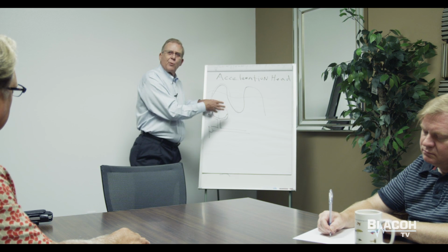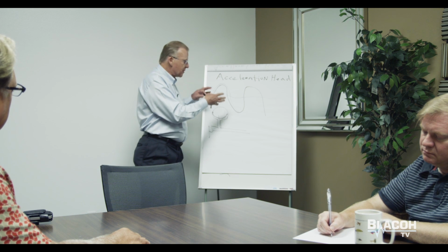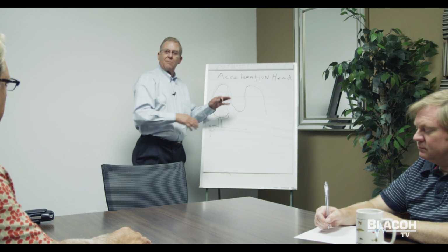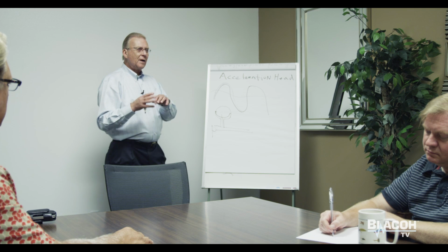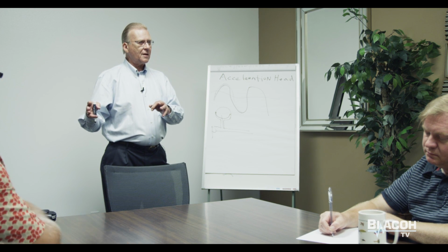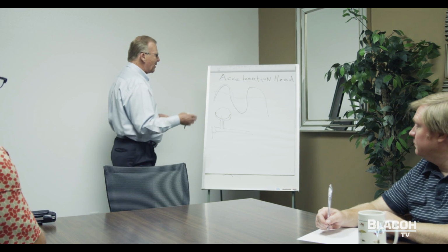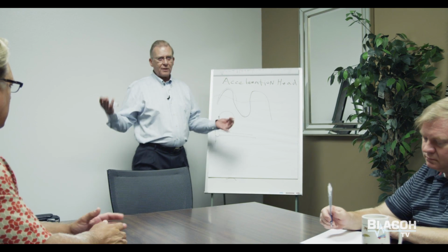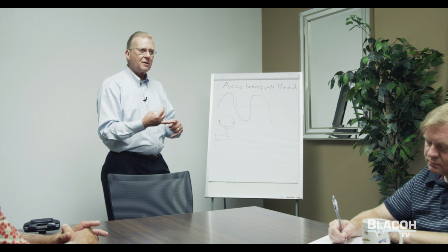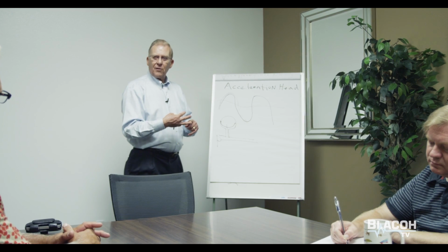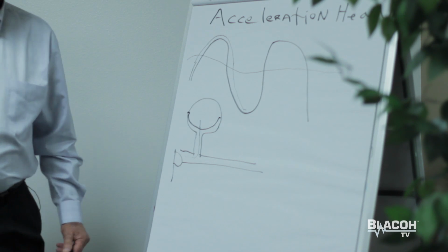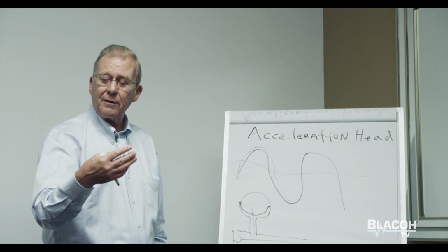We're using the pump's energy, but we're not losing it. We're just storing it momentarily and then reintroducing it back into the system. It's relatively easy on the discharge of the pump to overcome acceleration head or deal with it, because you've got the power of the pump, whether it's compressed air or a motor or whatever form of energy generation is attached to the pump. So even if you don't have a pulsation dampener, you have the power to do it. It takes more energy, but you have the power to do it.